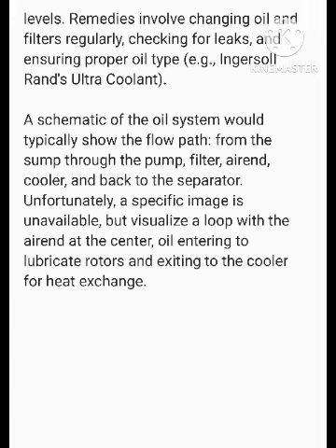A schematic of the oil system would typically show the flow path, from the sump through the pump, filter, air end, cooler, and back to the separator. Unfortunately, a specific image is unavailable, but visualize a loop with the air end at the center, oil entering to lubricate rotors and exiting to the cooler for heat exchange.